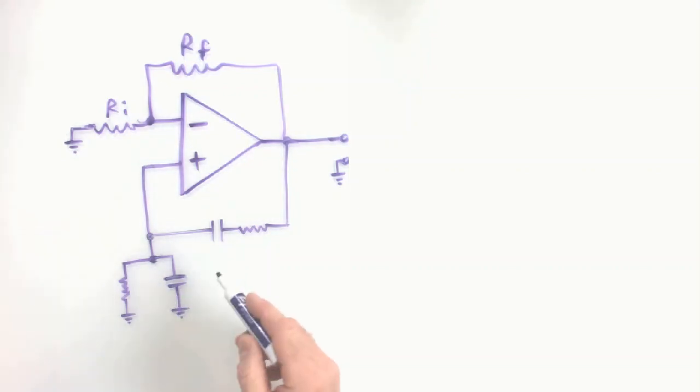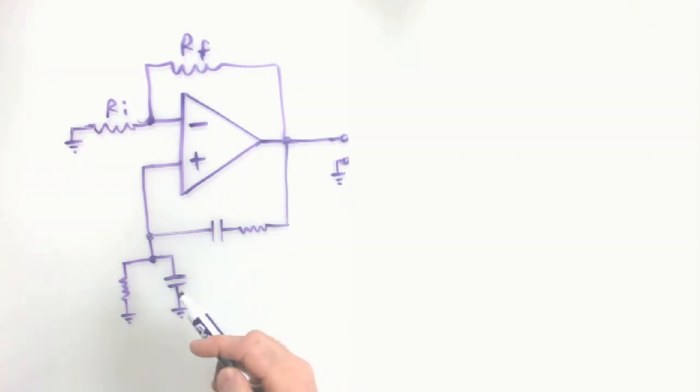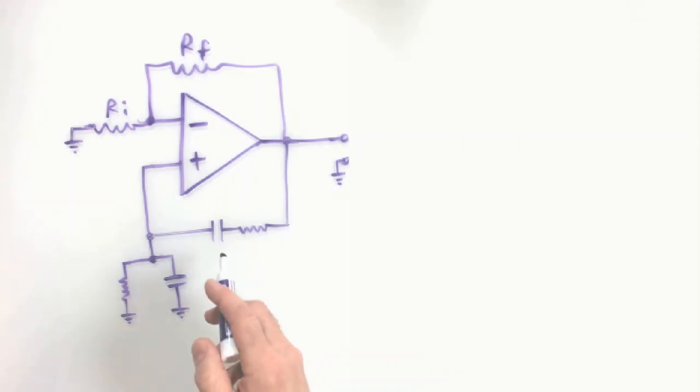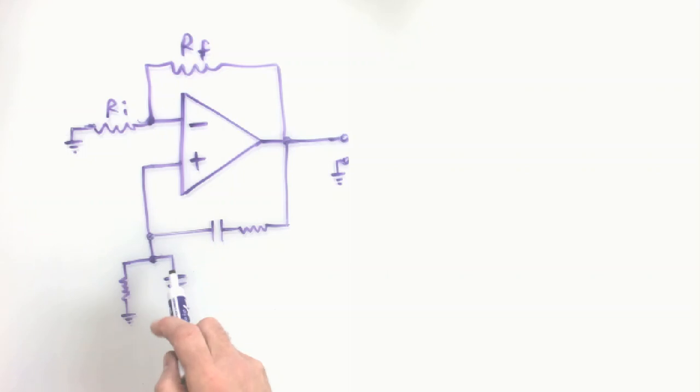This is that low pass, high pass Wien network that we developed, where we cascaded a low pass and a high pass. We found it interesting, at least I do, that you can rearrange that and have a circuit that looks like you laid them on top of each other, and it works the same. That's the Wien network. Anyway, it's a bandpass network.